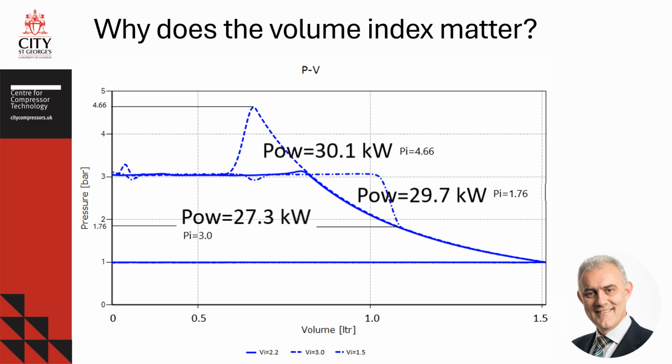The discharge port will open earlier than in the previous case, and the gas from the discharge plenum will rush back into the compressor to suddenly increase the pressure in the compression chamber. Further rotor rotation will push the gas out of the compression chamber at the discharge pressure. This is called undercompression, in which case the power consumption will be 29.7 kilowatts.